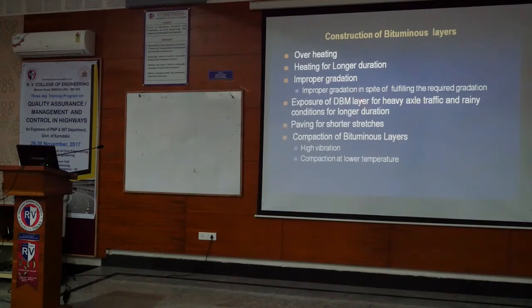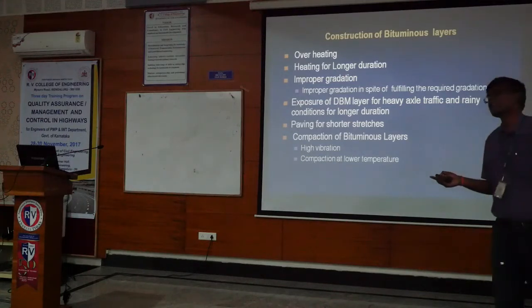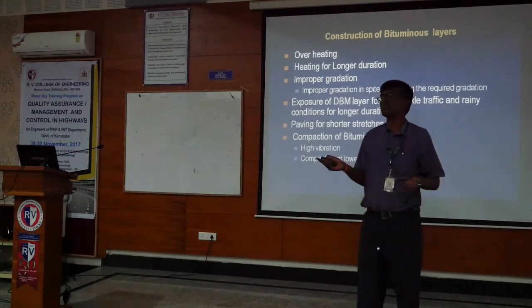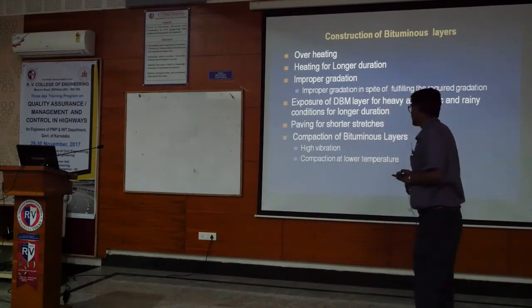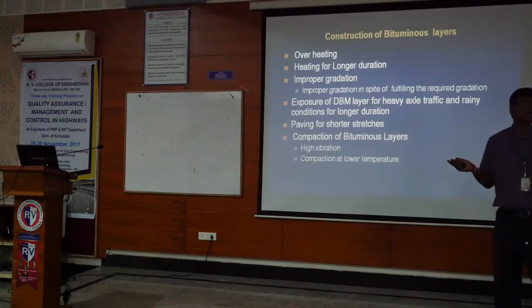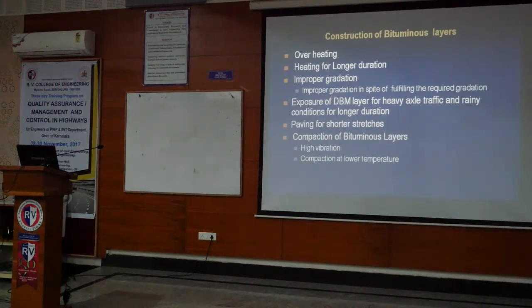And another important thing, exposing the DBM layer. Generally, DBM is also a dense mix layer, nothing to worry, but it is okay only for a short duration, and we can allow the traffic without covering with a BC layer. But exposing the DBM layer, thinking that it's a dense layer and it can take the load, no, it will not, and it fails prematurely. Life comes down drastically unless it is covered with a wearing course very soon.